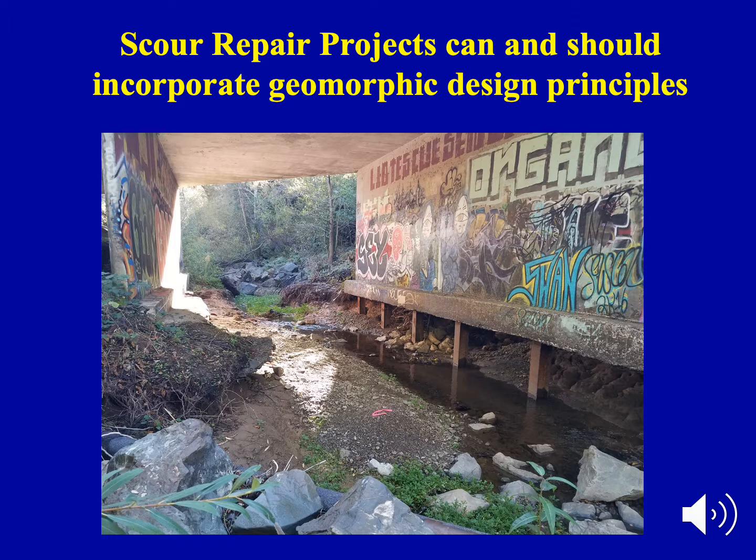And if you don't include your geomorphic processes in your design on a scour repair project, well, they'll come back and do their own thing and create scour either downstream of your project or at the project site. The initial solution at this mission critical scour bridge was to just fill the entire channel with riprap, footer to footer, across the whole channel. Basically make a 6-foot wall of riprap downstream.